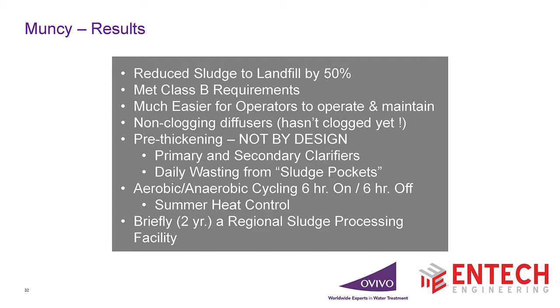Pre-thickening, which to me is almost essential, but we did it here, but not by design. Again, trickling filter plant, primary, secondary clarifiers, daily wasting out of sludge pockets, you're wasting relatively thick sludge into these digesters. First summer we operated it, it was extremely hot that summer. We were well on our way to 35 degrees centigrade, had the hatches open to release heat. We started cycling the aeration 6 hours on and 6 hours off. That was the first summer it operated.